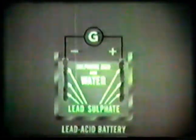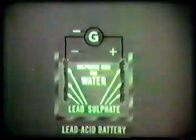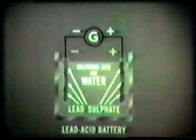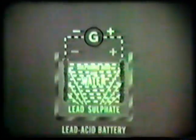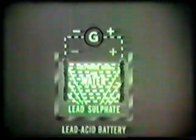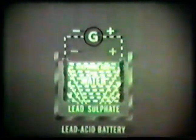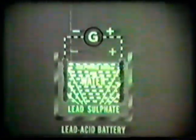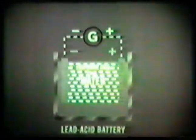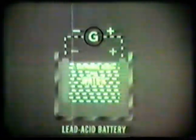The negative terminal of the charging unit is connected to the negative pole of the battery. The positive terminal is connected to the positive pole. Current is forced through the battery in the opposite direction. This charging current at slightly higher voltage than the battery's rating reverses the chemical reaction. The lead sulfate coating on the plates is changed back into pure lead and peroxide. At the same time, the acid is restored to its original strength. Charging is complete when the sulfuric acid strength is at maximum.